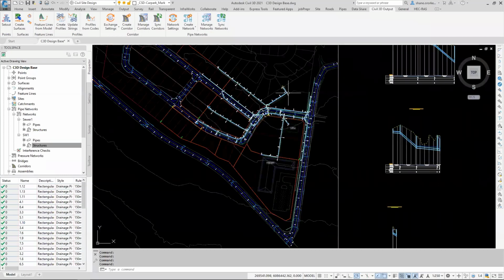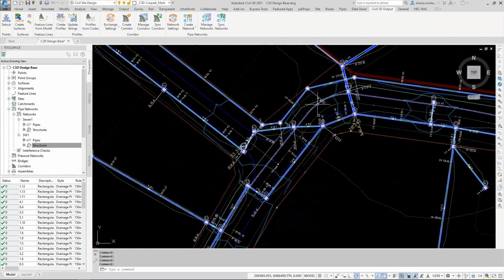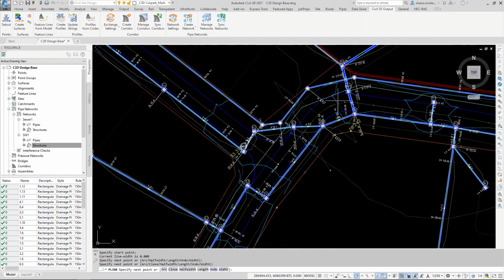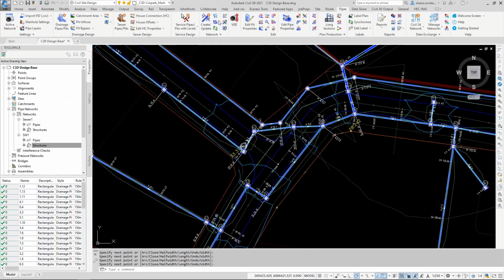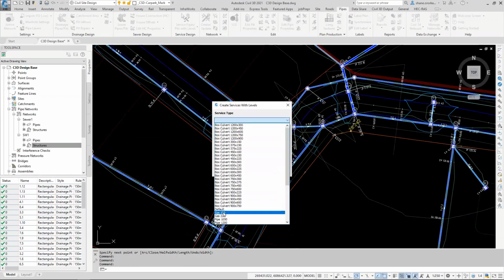Now, in civil site design, one of the values of civil site design is quick clash detection. So if I just create a quick polyline here on a very transparent layer that you can hardly see, we'll then be able to see a better clash detection scenario. So I'm just going to turn that into a gas line.